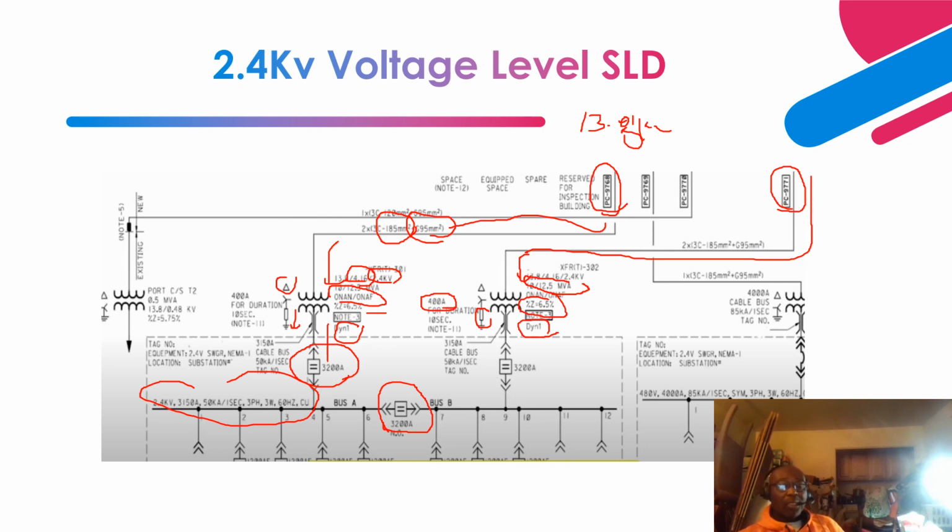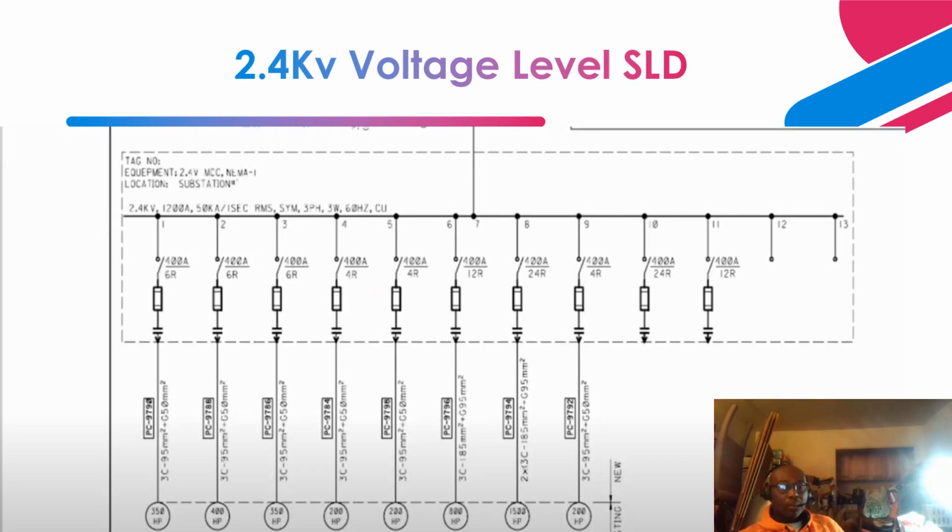Okay, so this is the high side vector configuration. On the high side, the transformer is wound in a delta configuration. So this is the incomer, right? The incomer breaker, and this is rated 3200 amps, and it comes in here. This is bus B, and basically bus B also has its cubicles that provide power to those loads.